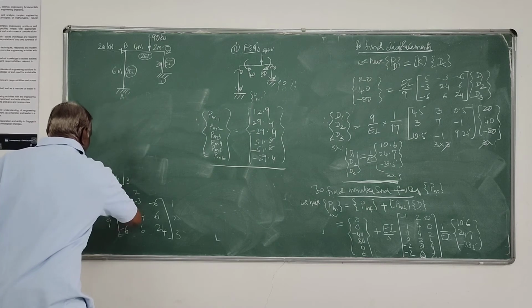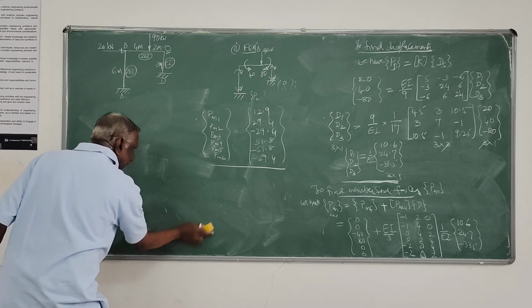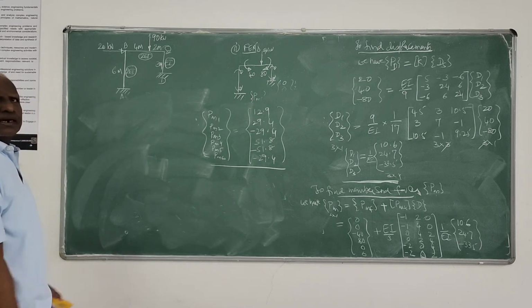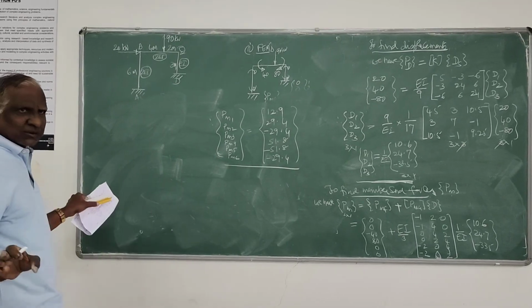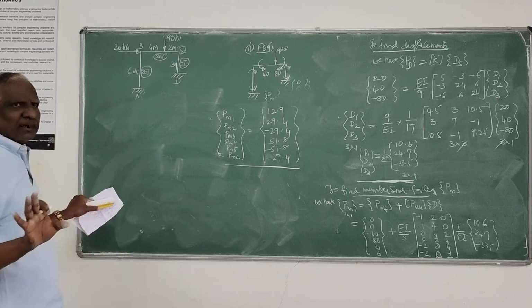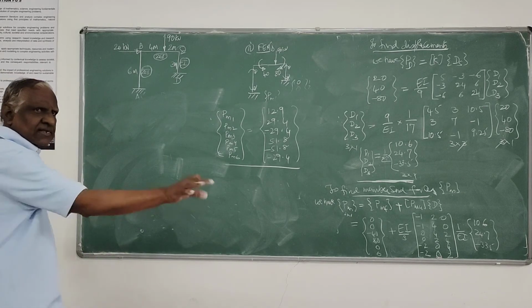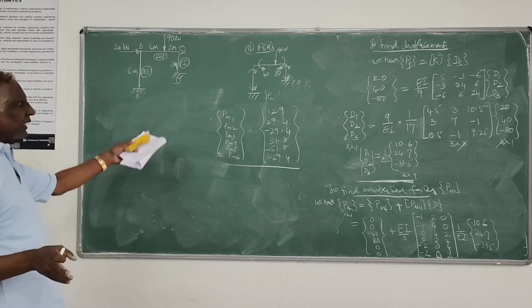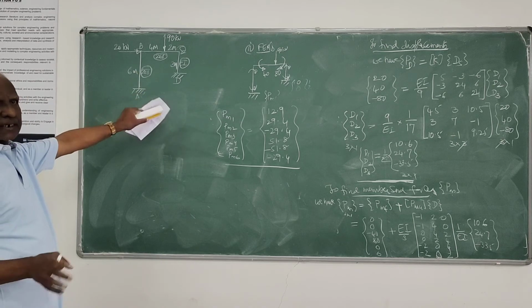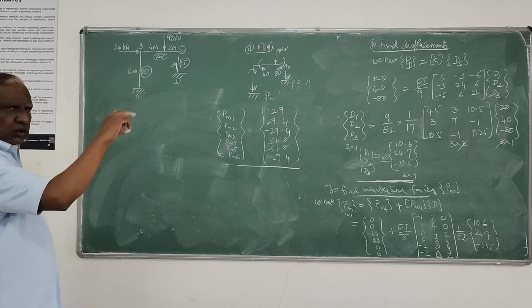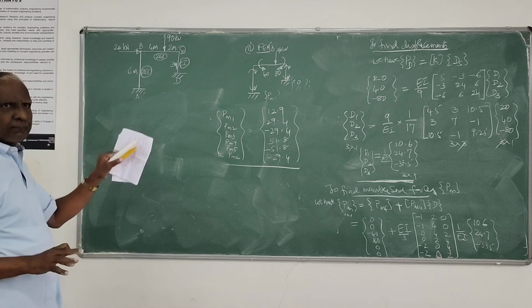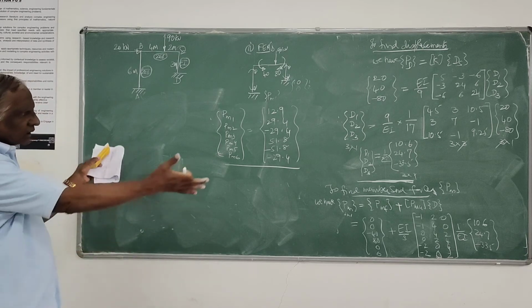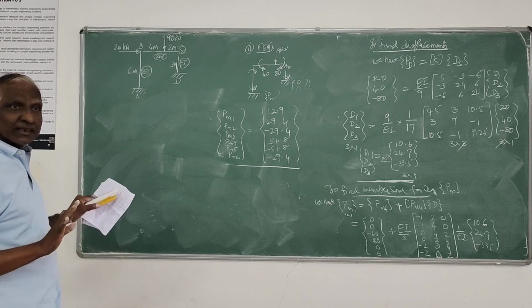Now finally you can plot the bending moment and shear force diagram. In this analysis, there is no question of sway, non-sway, and all those things. All unknown displacements at the joints, whether it is translation type or rotation type, we are marking. In the beginning itself, we are identifying unknown member forces to be determined, unknown degrees of freedom or joint displacement. So corresponding to that, we are doing the calculation.